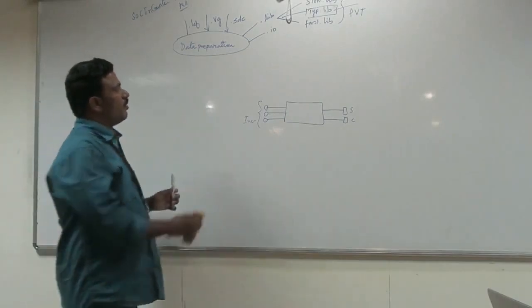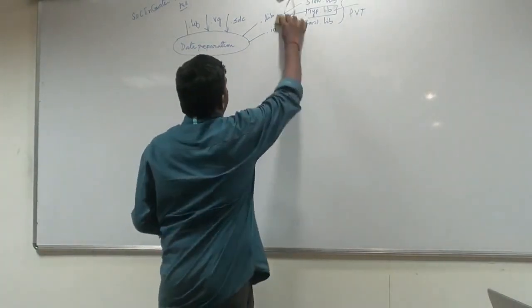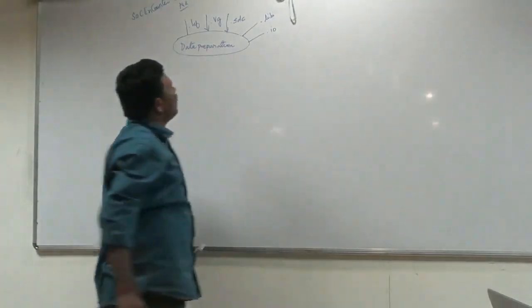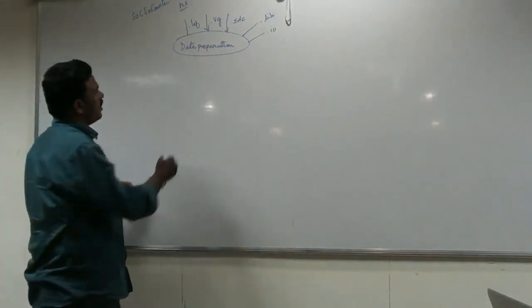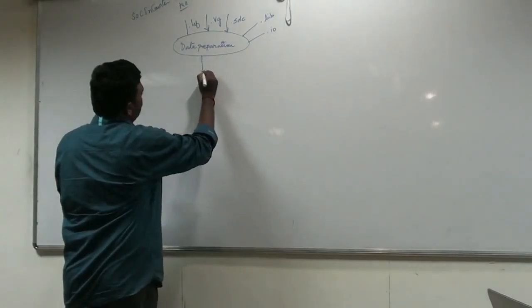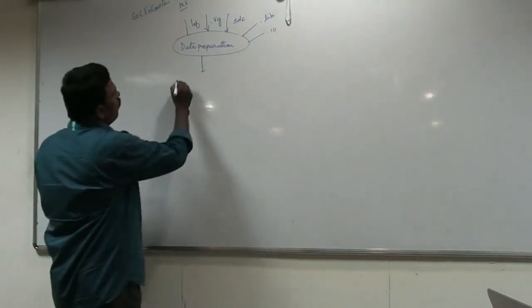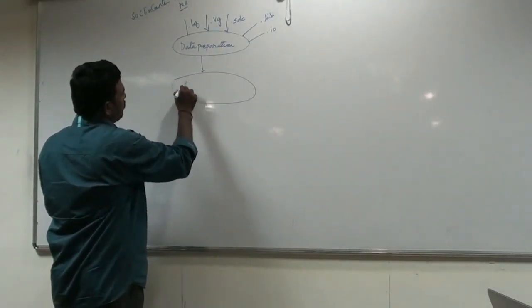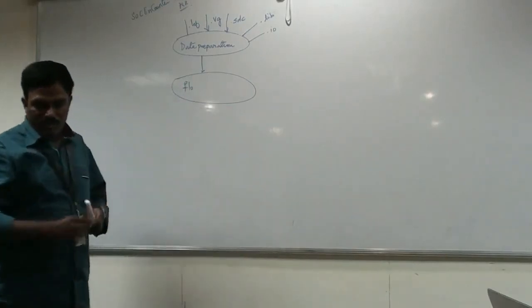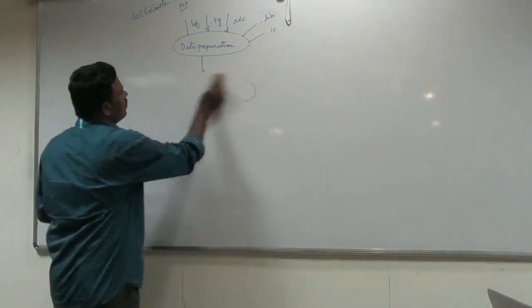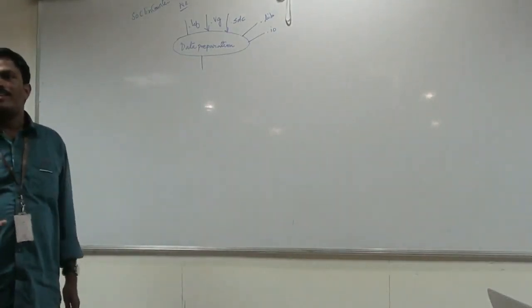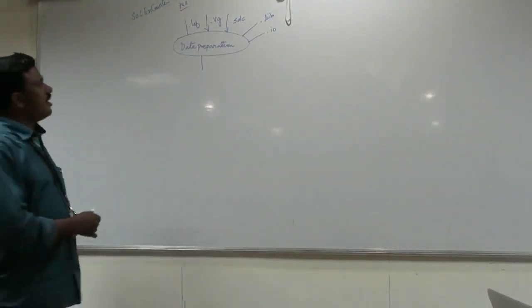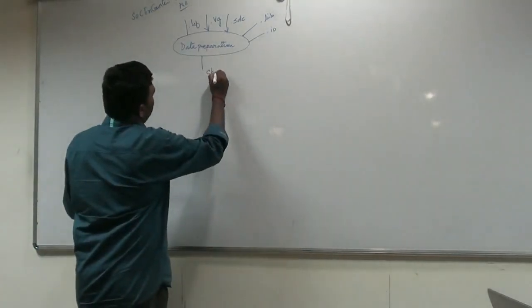Okay. Now, let me assume I have all the details with me. That is LEF, VG, SDC, .lib, .io, everything is there. Then the very first task in the backend, I need to go for floor plan. Before going for the floor plan, we need to check whether the synthesis fellow gave the right netlist or the right SDC, right?